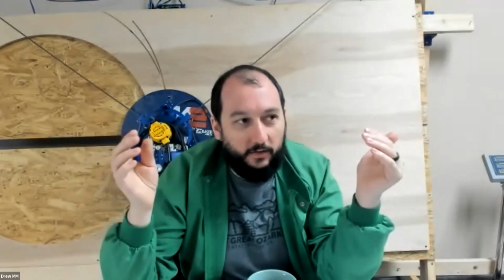So should I put the dimension of the full sheet, the 4x8 sheet? Yes. You want to put your full dimensions in Easel, and when you say you want it to be that large, like 2,500 millimeters or something, it's going to say, whoa, do you want to do tiling? It pops up with a little slider, and you slide that over, and that turns the tiling off. I bet that's your issue, because if it's not disconnecting from Makerverse, then it's something going on with the G code.